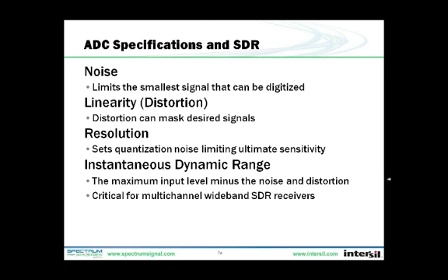Next, resolution sets the quantization noise and is expressed generally by the number of bits in the ADC. As other factors of noise and distortion improve, resolution ultimately becomes the limiting factor in performance.